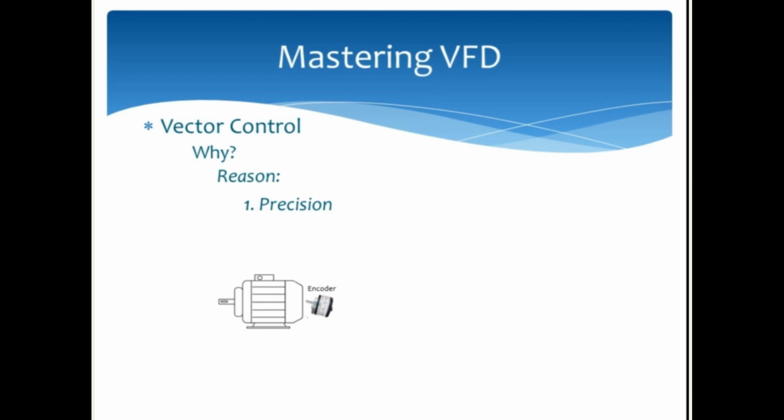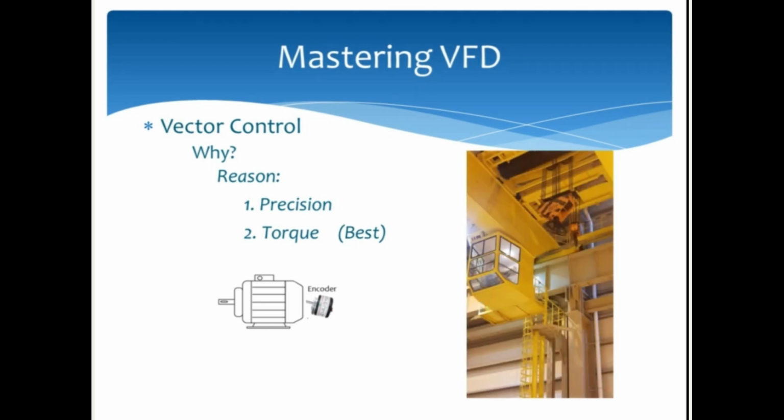The second feature, which is torque, that is the beauty of vector control. Since it can provide full torque at 0 Hz or 0 rpm. And that's the reason using vector control is known as similar to using a DC motor. With better torque, applications like hoist or crane will be easily set.